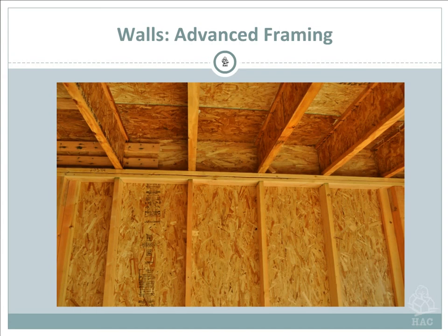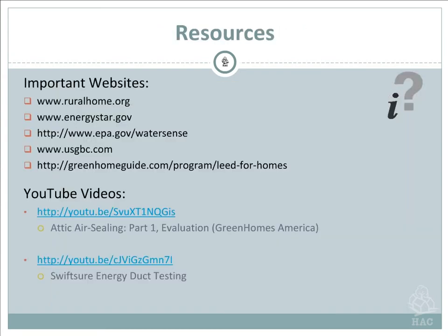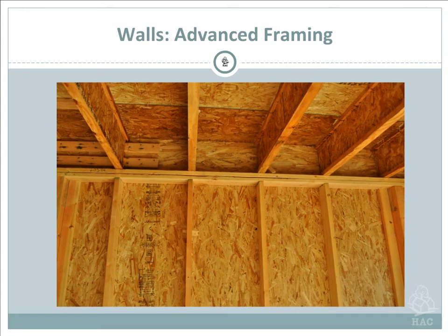The thing with this is you're going to have to use probably a thicker sheetrock. Probably have to go with a 5/8 instead of a 3/8 sheetrock just because of the spacing of your 2x4s. Again, there's different things that you got to take care of. One of the things is your corners. What I call a California corner. You need to make sure that those corners are framed in so you can insulate them. You can't have those three-sided corners anymore. What I call a California corner, it's easy to, just Google it, look it up. It's easy to do and it's easy to insulate. Along with advanced framing, benefits of advanced framing, pros and cons, it'd be a good idea to look at that.